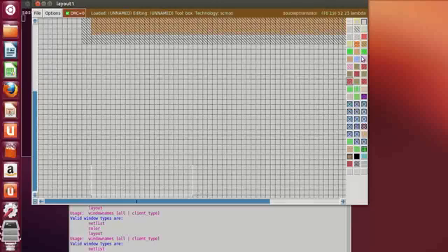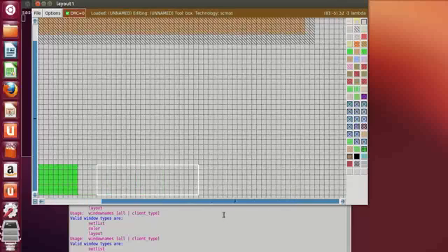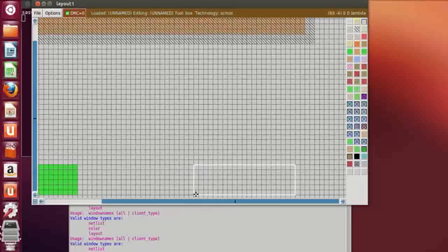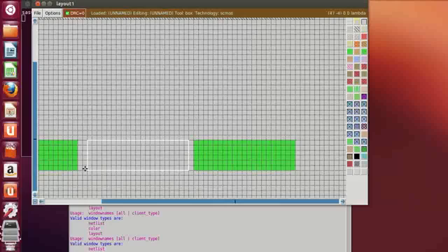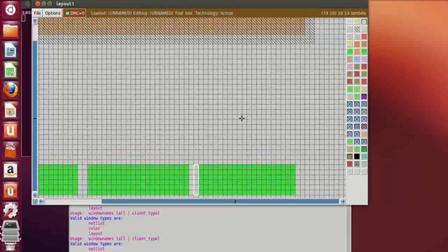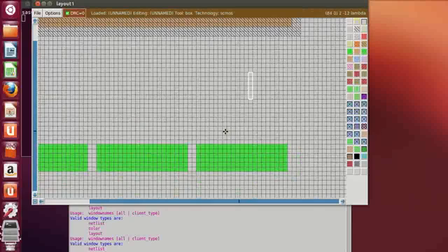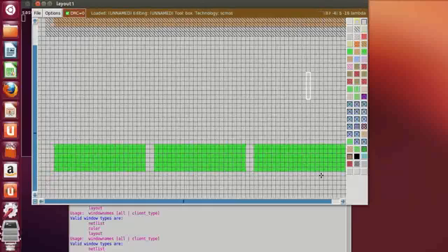So select the area and then middle click on P diffusion, sorry, this is the N diffusion layer, so N diff. Then this is the second one, then middle click on N diffusion, then we'll click on N diffusion. Okay, now since the three NMOS are in parallel, we have placed them separately.